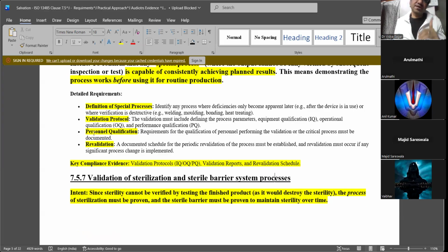Because just in one run you can't get it. You need to do 10, 15 runs, 10, 15 process parameters. Then you'll select which one you are very close to. And they also should have some knowledge of statistics, root cause analysis. If it is not happening, whether the temperature is affecting, immediately they should try to adjust the temperature. It's not that you blindly run 100 experiments.